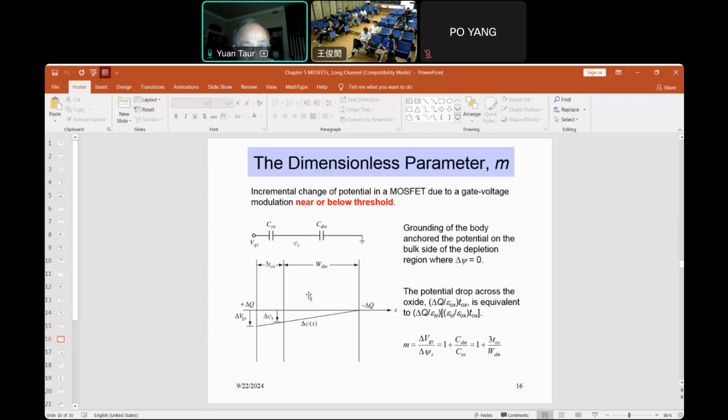Now, if we want to show this graphically, because there's a factor of 3 between the two dielectric constants, we make this 3 TOX. The 3 accounts for the dielectric constant ratio. Okay. So now we can have a straight line instead of a line of changing slope.